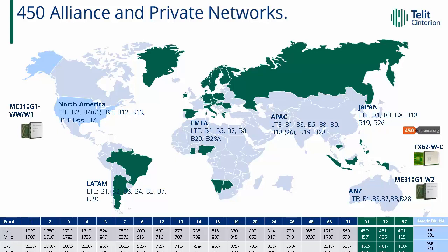the frequency band, at least sub 1 gigahertz. And in Europe, for example, band 20 is the most common. In the US, 12 or 13 maybe. So due to the lower complexity of MTCs, all the modules support all the bands globally, and rarely is there a need to make a specific variant for public networks for band coverage reasons anyhow.